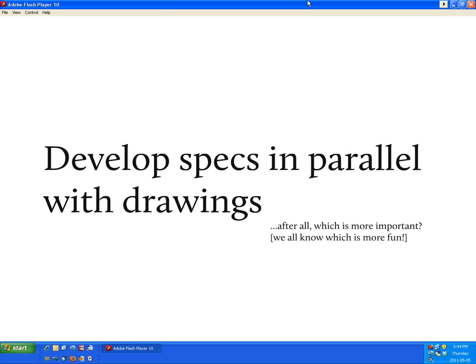Right. Here we get to that distinction that we tried to draw earlier between the basic material and a system. What I encourage folks to do, and maybe not everybody would agree with this, is have the leader point to the metal roofing and maybe even call it manufactured metal roofing system or manufactured metal roofing, to imply that it is a system and it has multiple components that go with it.